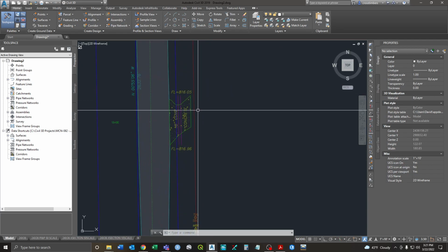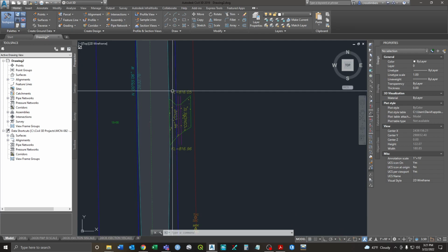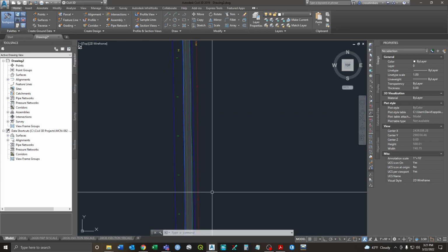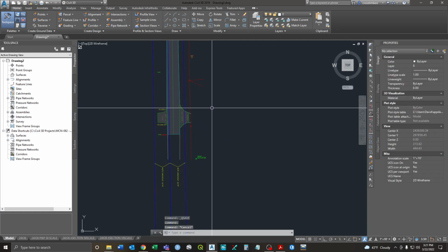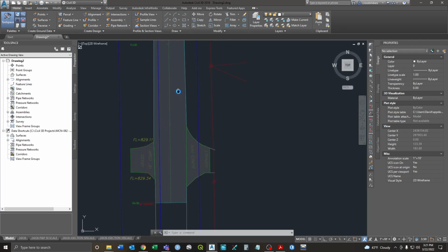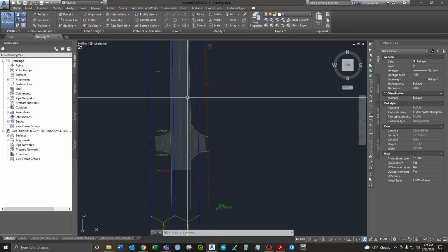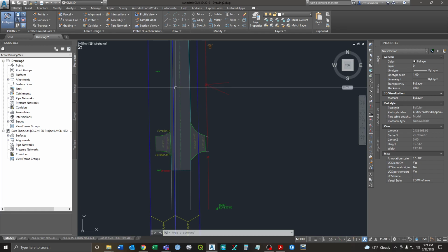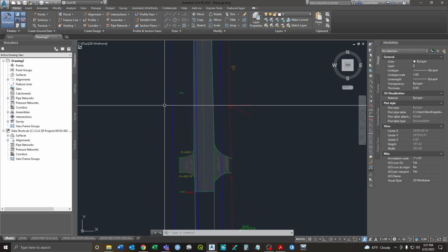So I don't know if Dad mentioned just some of these driveways, but that'll be something too that needs right of way. So this is statutory right of way, so I don't know if he explained that. Basically all along a section line, 24.75 feet out, that's statutory right of way, and basically that was bought whenever they started. It's just owned by the state or whatever. But you can see how the roads, even though they're section line roads, they don't always do a very good job staying on them. So your right of way is not always from the center line of the road, it's from here.